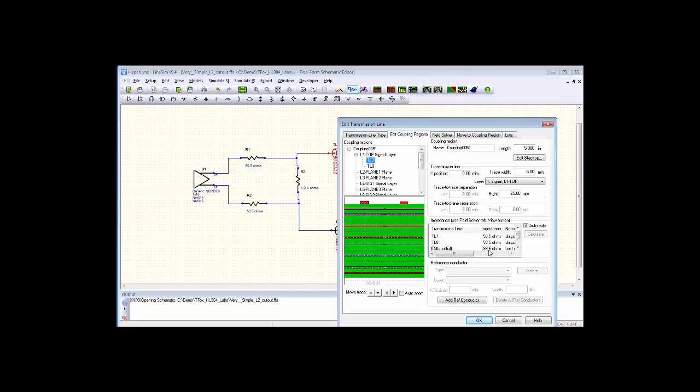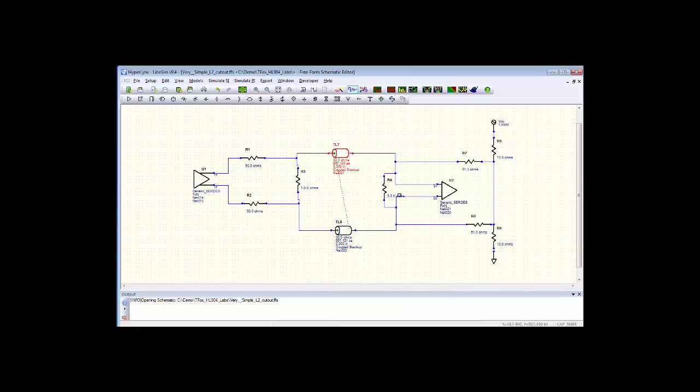It says the differential impedance is 99.6, but the resistor I've got across here is looking more like 3.3K, because we're actually terminating right through these two resistors. So this is just a larger resistor. This is now looking like 3.3K in series with about 102 ohms or so.